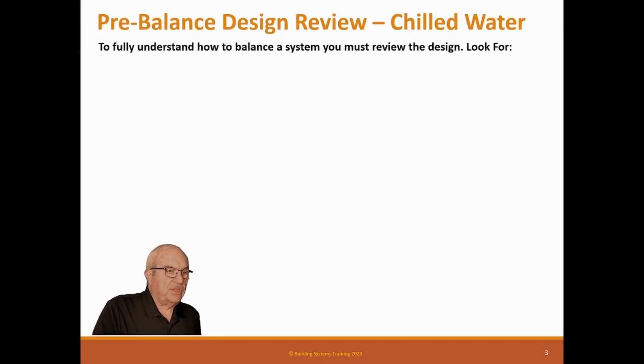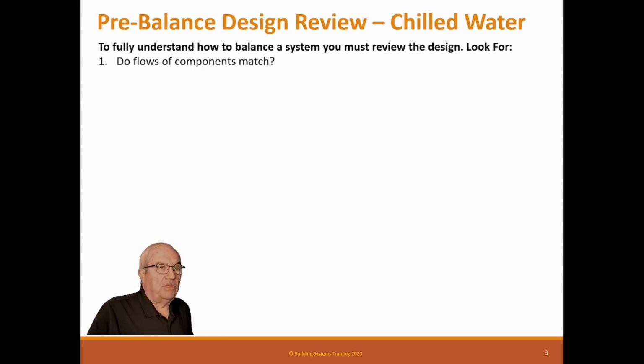Okay, so the first thing you always do on a job whenever you get there is you have to do a pre-balance design review. To fully understand how to balance a system, you must review the design. These are the things you normally look for when you do design. Do the flow of components match? And this is kind of important. The chiller evaporator flow to the primary flow, those need to match.